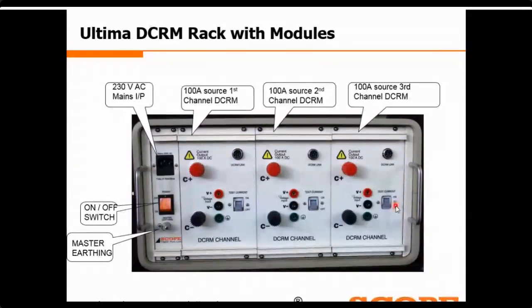Secondly, the beauty of our equipment is that we can measure the PIR timing. As we have developed this equipment indigenously, we can design the measurement of the PIR timing. Even with a PIR resistance of 1 kilo ohm, we can measure the timing. So our kit can successfully measure the PIR timings of AIS circuit breakers and GIS circuit breakers also. It's the beauty of our equipment.